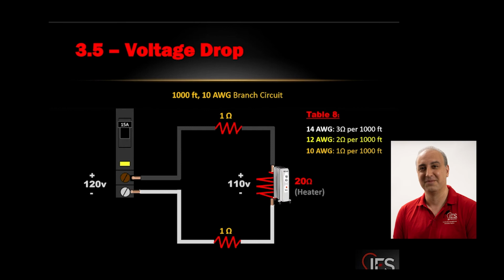And you want to do that even before you do the bids or proposals, right? Because if we bid the job with a 14 gauge to every home with those garages on the other side of the yard, and then we figure out, no, we need to upsize, we'll have to eat the cost that comes out of our profit. But if you see that before, when the proposals are done, going to the builders, we're estimating the cost of the job, we give it to them, they pay us for it. So you have to keep these things in mind.